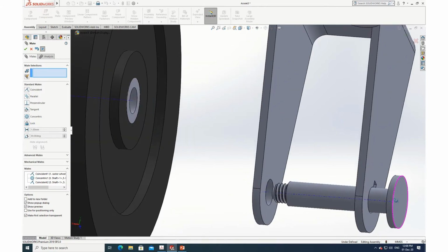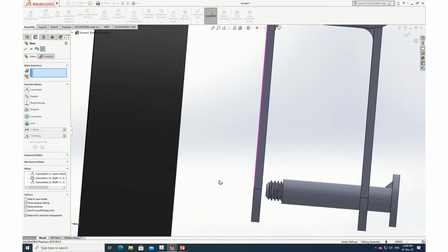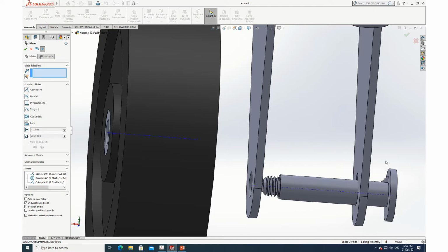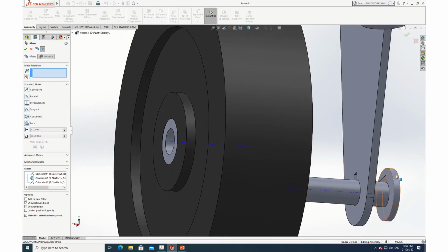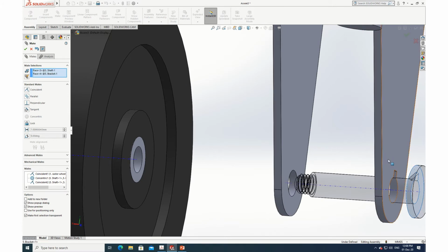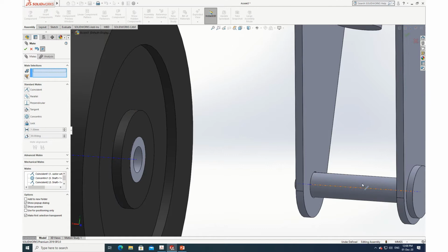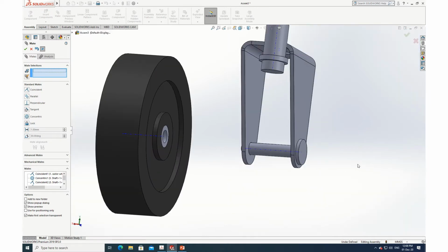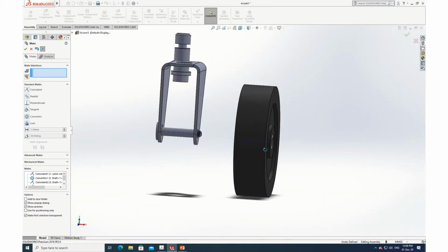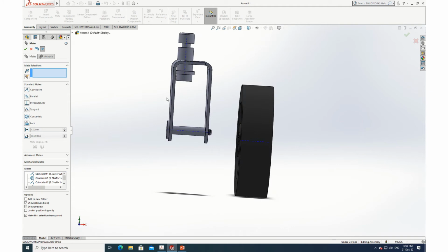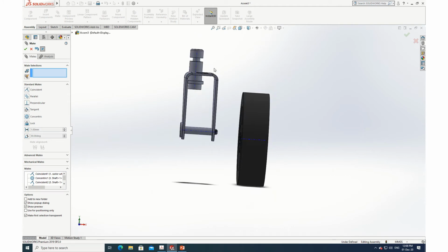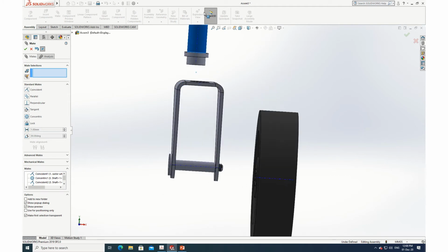I cannot turn the shaft now. So the next one what I will do is, I will make this surface. Where is that? This surface and this surface I will make it coincident. Good, done. See there now, already everything is there in place. Let me turn it this way. Now what I will do is, let me make it a little small. I will take this one up.